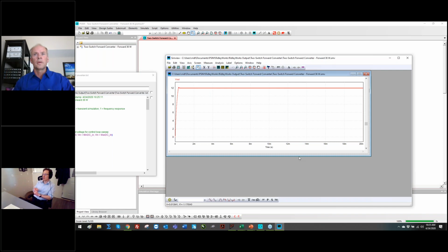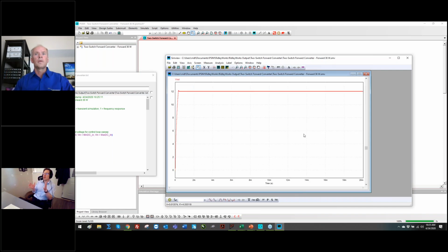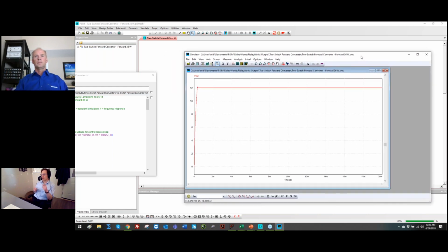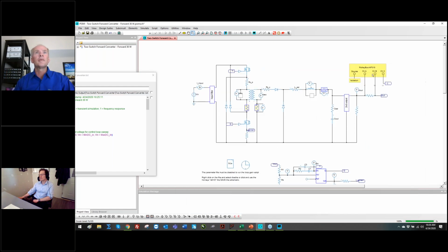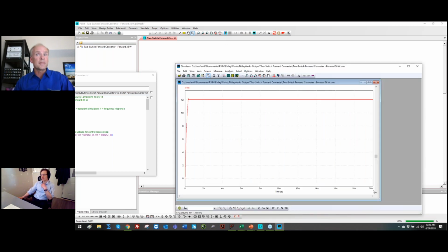With the Psim templates, it's one circuit, and in the parameter file there's a setting that you change, which Ray just did, to toggle between the transient and then the sweep. Right, exactly. So here's our transient inside Psim. Let's run that again, so you get an idea of the speed. That's 1 second, 2 seconds, but we're doing 20 milliseconds inside Psim. So that's 4 times the length of simulation that we did inside LT Spice. So that shows you the speed that you're getting here.